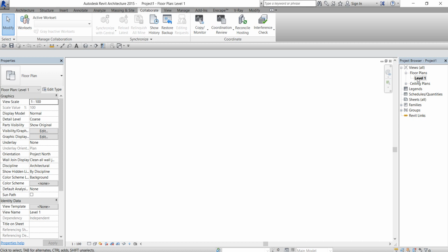No matter what we go to, we can decide to draw whatsoever we want to draw here, but elevations are not going to show. But we are going to set all those things and put them in place so that by the time we are drawing, we are going to be seeing what we are doing, because that's the function of Revit. If you work on Revit, the moment you are drawing a plan, it definitely gives you the advantage to view your elevations so that you are not going to get lost. At the same time, you can be viewing it in 3D automatically.